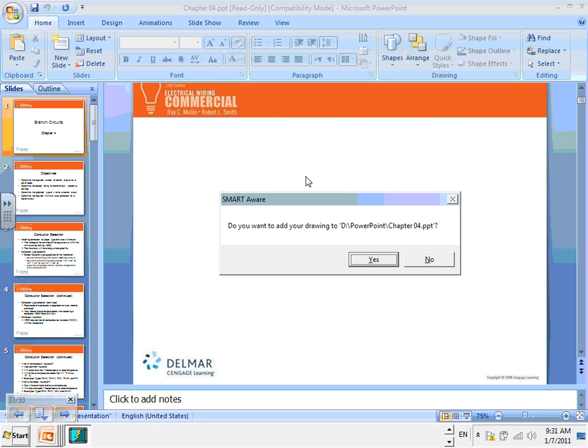And the conductor size is number 12, right? Because we could have done with 14, by the way, looking at the 9 amps, but we don't want to do that. And then the ampacity of the conductor is 16 amps. If it's continuous, how much current can you get out of it? Number 12, if it's a continuous load, 16 amps, based on 20 amps.